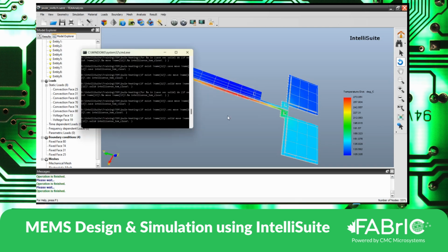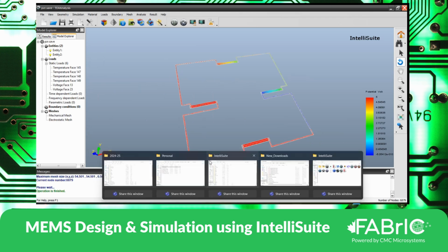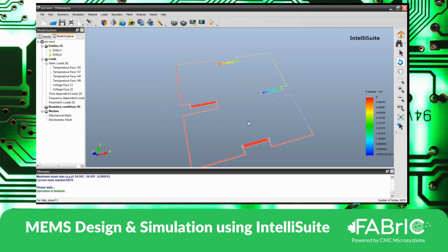Okay, there is one question now. Almer is asking, so the software will understand by itself the maximum temperature caused by the voltage, and it will compare it with the 25 degrees to get the heat gradient of the convection process? Yes, that's right. Absolutely. Wherever the geometry gets connected, in those connecting regions, some regions are based on the voltage that is applied and some regions are based on the temperature around it.